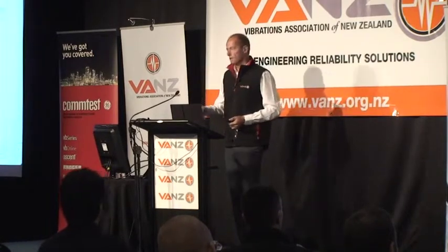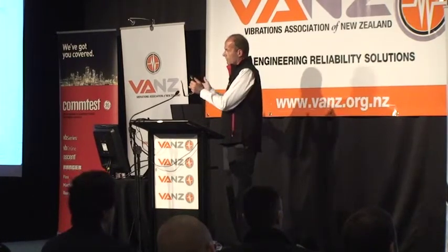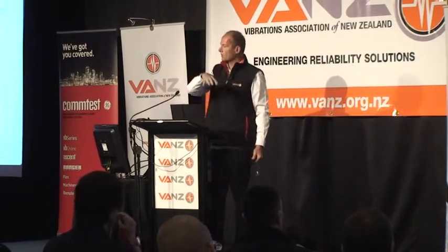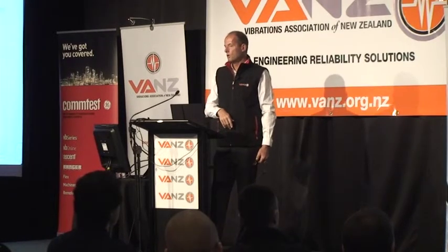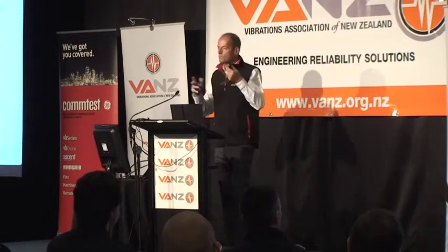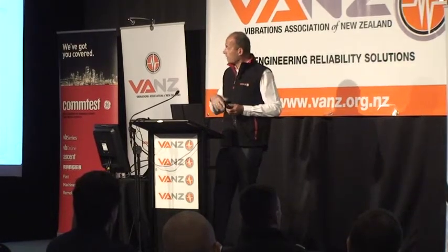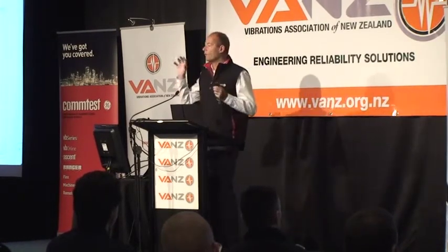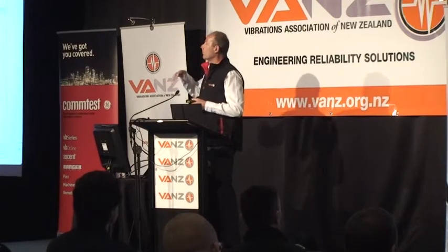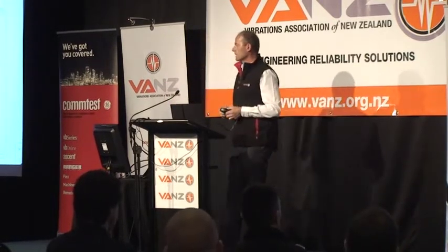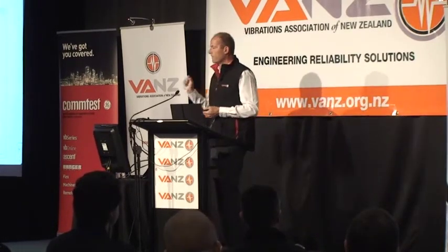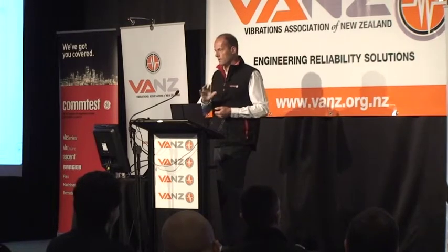through electrical tests. And those tests can be performed while the motor's offline, like while it's still in stores, and you can check that it's actually fit for purpose, and you can test it while it's operating as well. So there are lots of tests that's sort of more on the electrical testing techniques, looking at resistance, impedance, and these sorts of things. But it's amazing what you can learn. And again, it's all about avoiding those problems, avoiding the failure. But in a case like this, we are detecting problems that exist. We're not necessarily preventing the root cause of the problem itself.